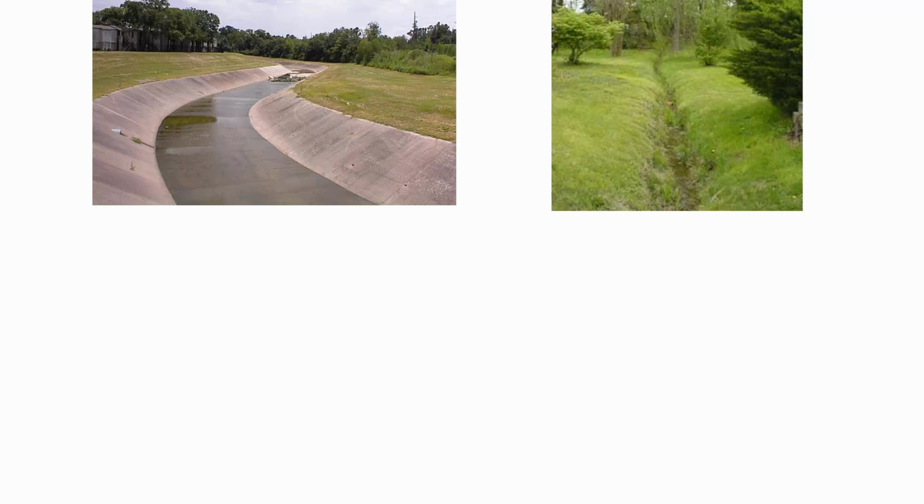Sometimes we consider water as a waste and we want to promote infiltration. If it's stormwater runoff, then we'd much rather have the water infiltrating into the soil than concentrating at some central location where we then have to build a pond or be concerned about flooding. But in this case, most likely what we're looking at is an irrigation canal, where avoiding infiltration is really important, because every drop of water that you lose to infiltration is a drop less that you have available to use downstream for watering plants.